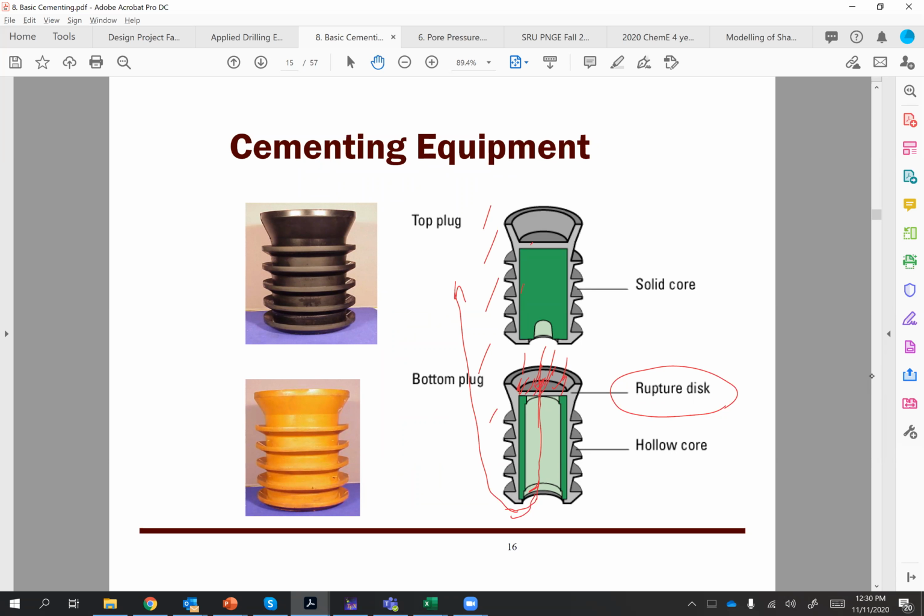If I want to draw the wellbore exactly right on this, you will have some volume of cement here at the bottom, and the rest will go all the way to your annulus, right? And once your cement is set, you want to restart drilling, so you drill through all these components. And that's it, right?